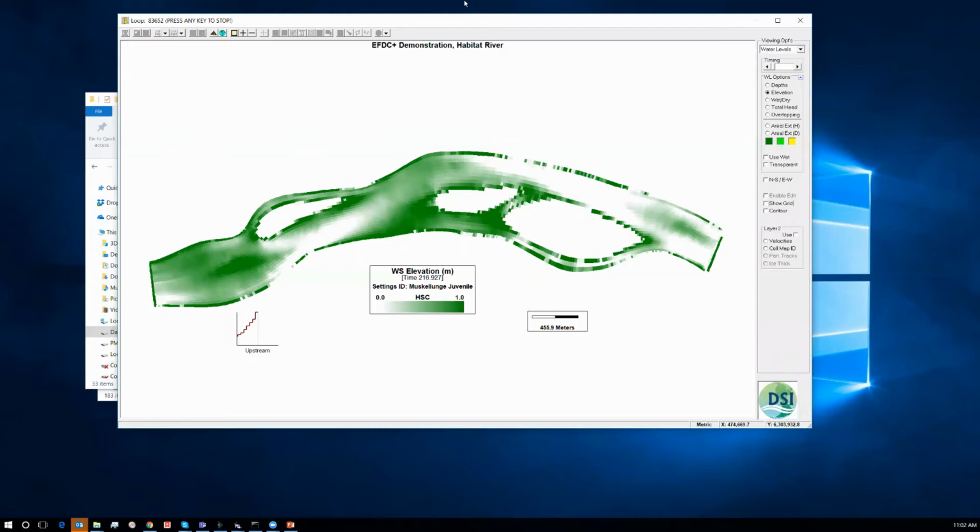You've got to simulate at least one algal class and your organic carbon content, your phosphorus family, your nitrogen family. So for a full eutrophication model, it takes a minimum of around 14 parameters. So you can't include all of those in one of these analyses.